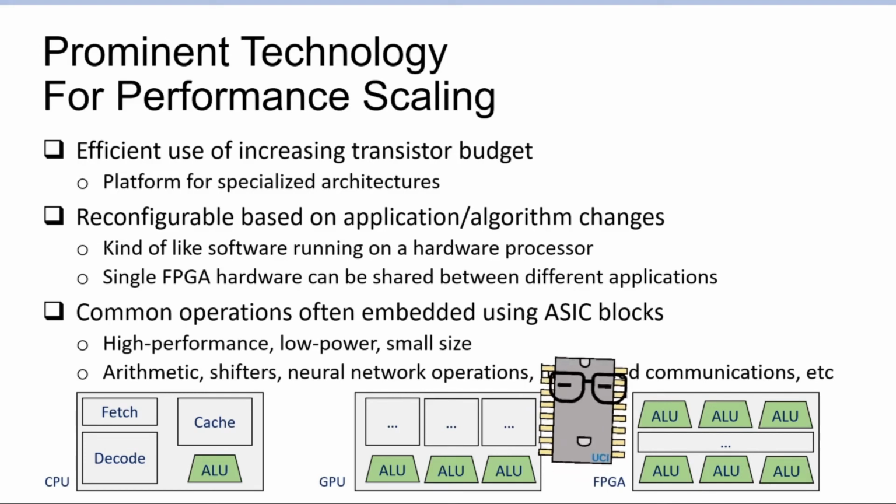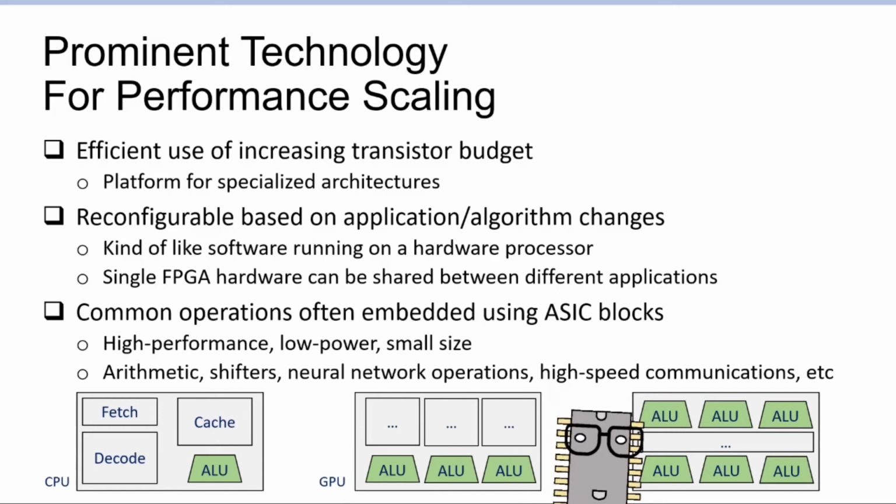And because we stopped trying to be general purpose, instead we aim to support general purposeness by reprogramming the FPGA if the application changes. That's how we try to get general purpose, not by having a single design of silicon be general purpose in and of itself. So FPGAs try to get, the goal at least, is to get more ALUs on the same chip resources, doing more useful computation, and have much less surrounding infrastructure taking care of all of this.